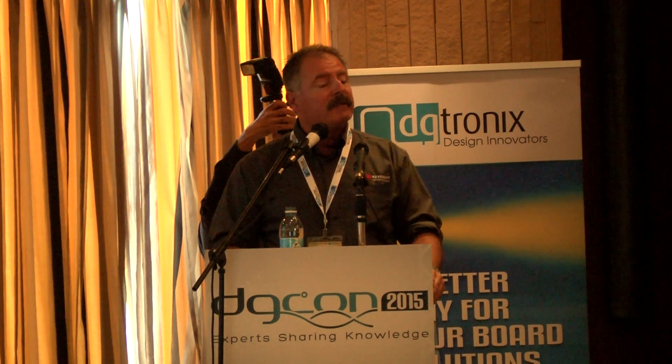Now, with the TRL cal kit, TRL, through reflect line, those are three standards that need to be designed and fabricated. And for the L, there's usually more than one: line 1, line 2, line 3, of different lengths that correspond to different frequency bands over which you're removing the test fixture, making the measurement. Honestly, I know that there's probably 10 or 20 companies that are very good at this on PCB, but it's not easy. And it's usually not something you get right on the first board turn.